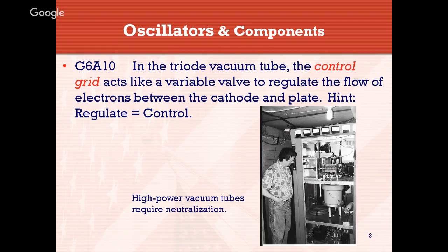It has a smaller tube for the driver circuit, and then it uses two other tubes for the final output power. Typically, 12BY7s are a typical driver type tube, and 6146Bs are a typical power output tube. It gives you 100 watts.